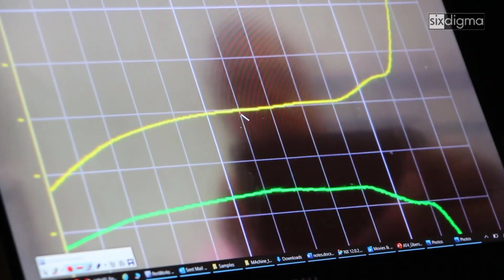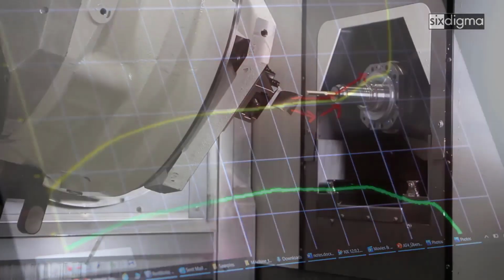This is the toolpath trace after the tool axis reversal was corrected. Here you can see that the main rotary axis always moves in a clockwise direction. In the previous example, before the correction, at this area, the graph dipped and then picked up. Here you see that we were able to correct it and continue with the positive clockwise direction of the axis, which produces a much better result.